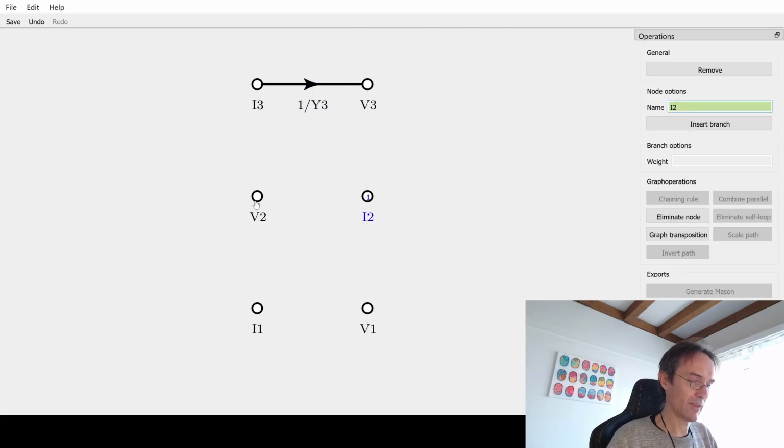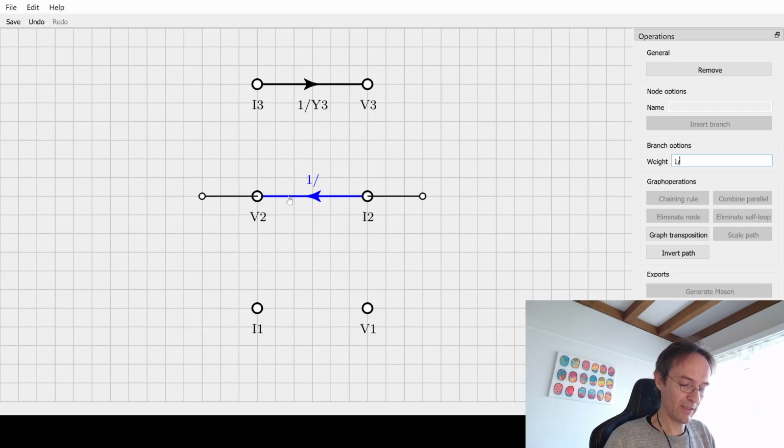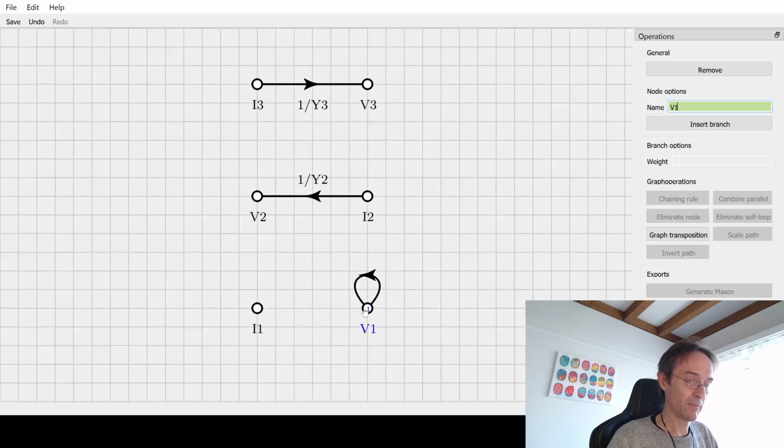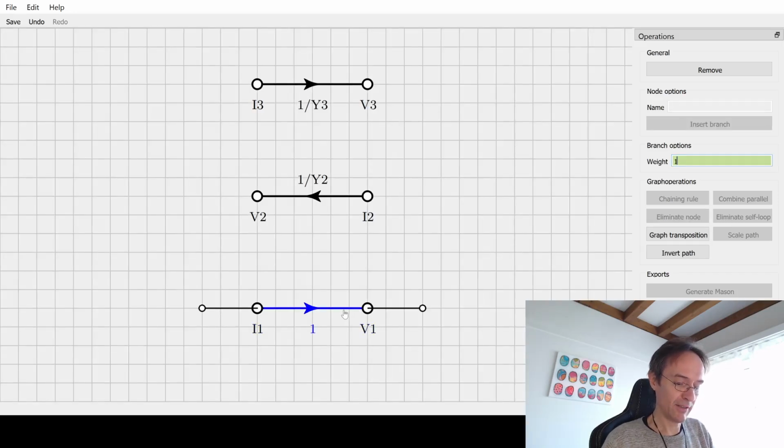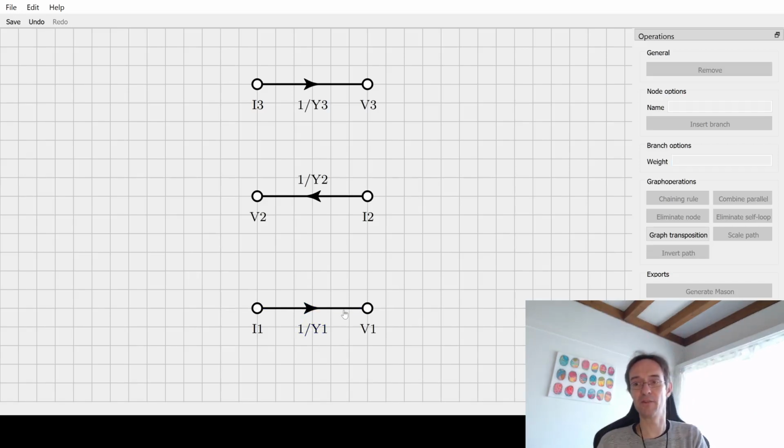And you see that I'm doing something strange here. So the paths I draw, they go left, right. So they change directions. But as those of you who already are familiar with the signal flow graphs know, it doesn't matter in which direction a branch goes on the paper, because these are just relationships between variables. The reason why I draw it like this here really is that I know if this goes like a zigzag here, then I will get fewer crossing branches on the paper, and the whole signal flow graph will be more pleasant to read in the end.